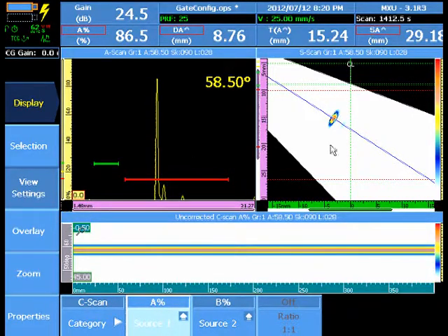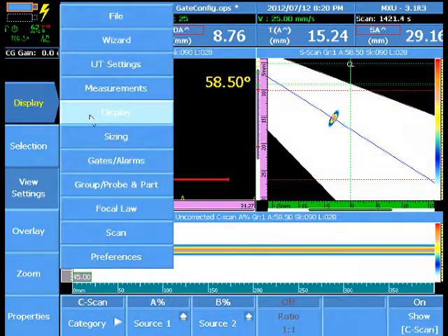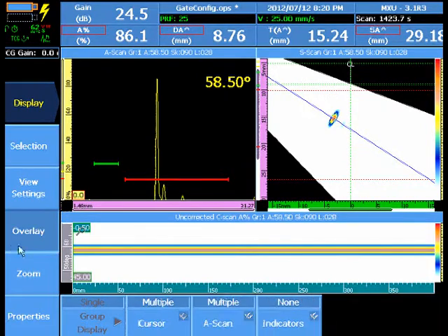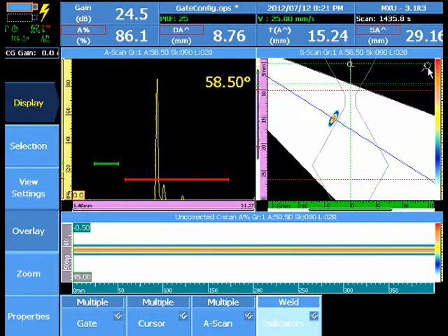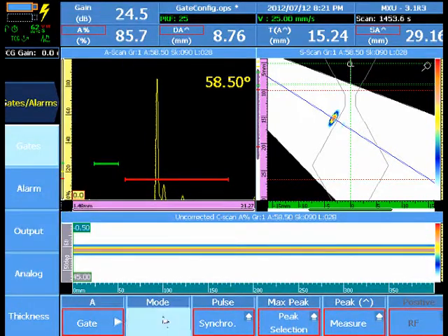When we set the gate position for the weld overlays, using the weld overlays for a weld inspection, we want to start the gate position where it enters the weld initially. When on a display that can display gate A, when the touch screen is in gate mode, the gates can be dragged and dropped directly on the screen. From the gate menu, the parameters can also be manipulated.